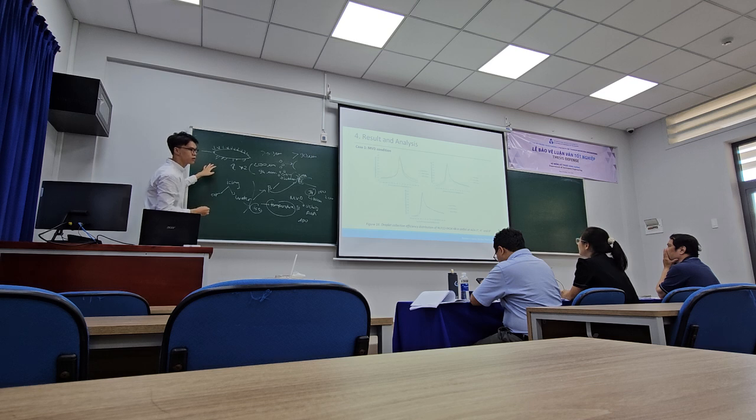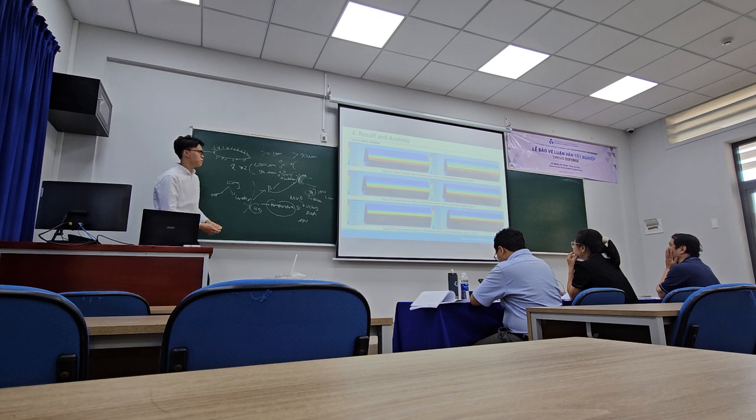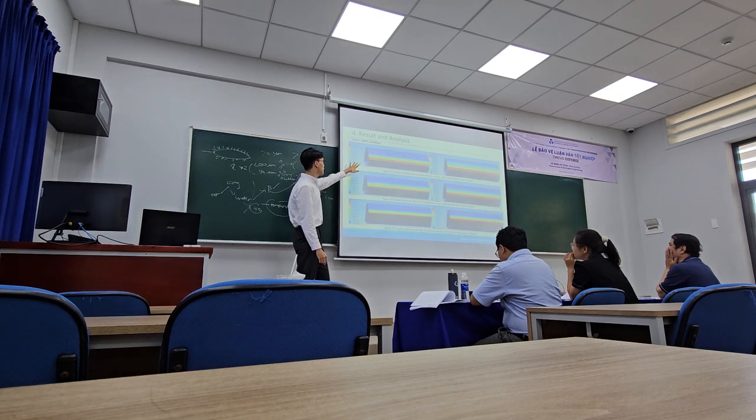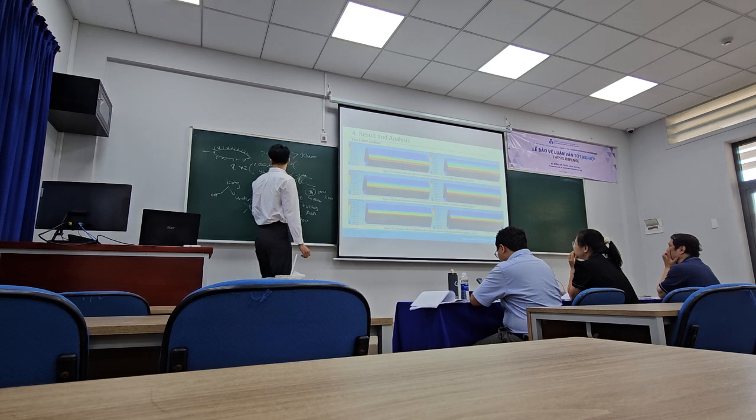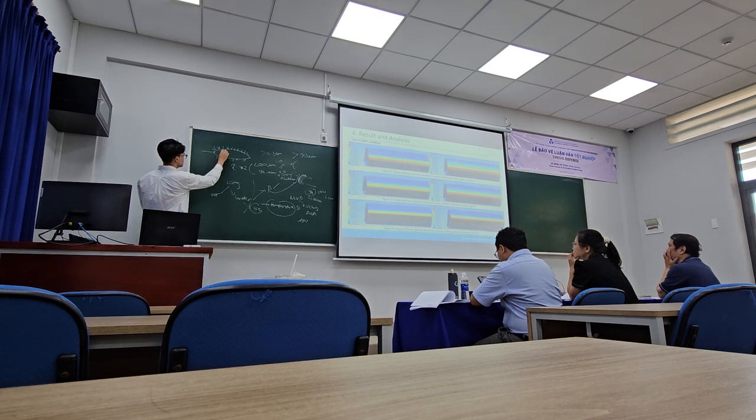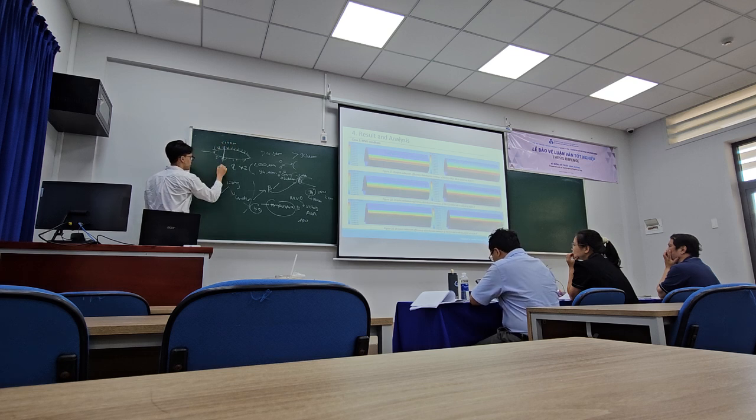The highlight. What do you mean by highlight? Is there any definition of that kind of highlight? Do you have some sketch or image or pictures that show the highlight? Highlight point means that at 0 angle of attack we have the highest collection efficiency. So we will check this and survey from 200 millimeters of the upper surface to 200 millimeters of the lower surface to survey the collection efficiency.